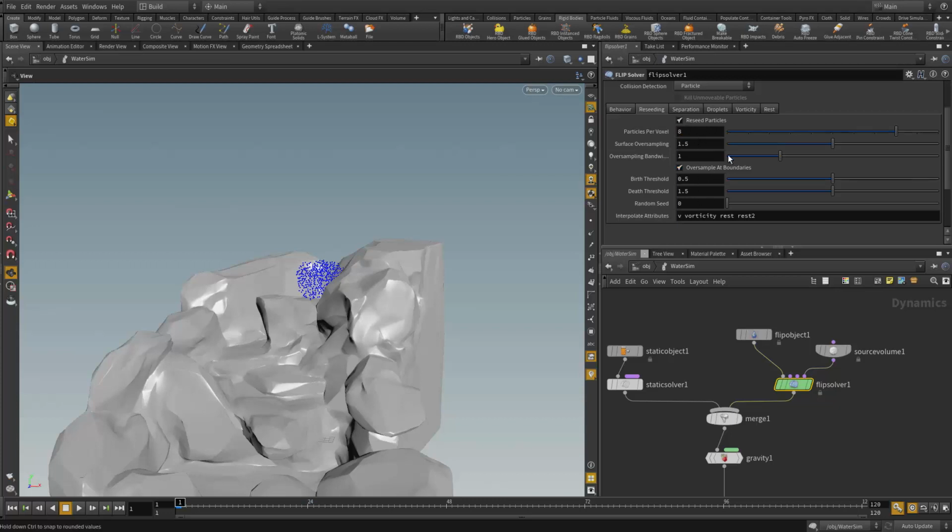Now some of the settings down here are controlling, for example, this burst threshold. There's some mathematical thing happening, which is that particles will be added to the voxel once the current number drops below the product of this parameter and the goal number, which is this guy. If the product of those two values is getting too low, it will start fitting in, just generating new particles.